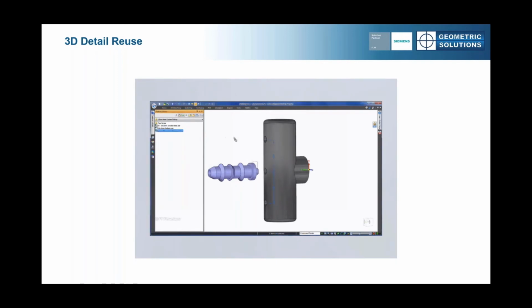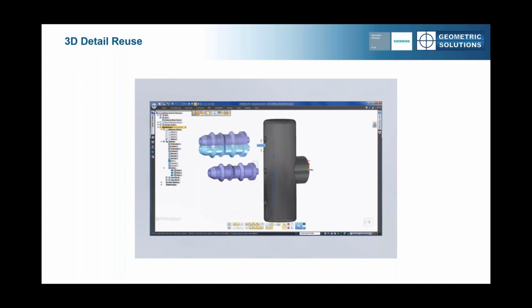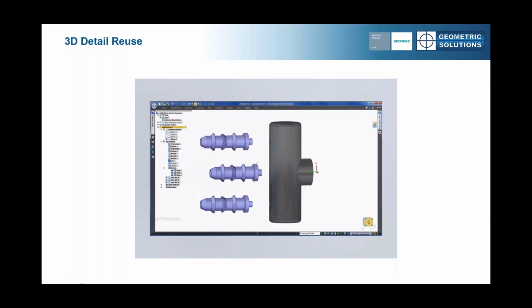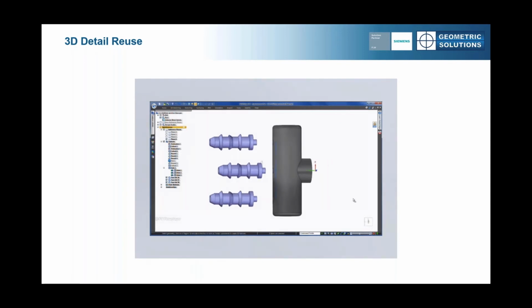The steering wheel can also be used to enter precise offset values. Here we'll offset it exactly 15 millimeters and then snap the barb into place. Additionally, by holding down the control key while we drag the steering wheel, we can copy this barb to the other location required. Again, notice the familiar use of Windows shortcuts. Holding control in Windows does the same thing, copies, quick and easy.